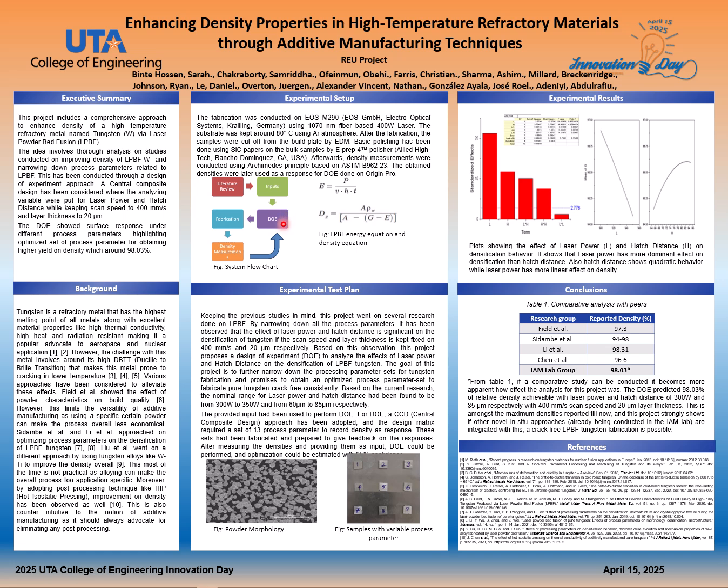We performed the DOE. We did the fabrication on an EOS M290 machine. Then we measured the density following ASTM standard B962 section 23, and then again we gave it to the DOE to find the predictability and the performance of our analysis. Based on the research that we have conducted, we found that they all agree the scan speed is more or less 400 millimeter per second and the layer thickness is 20 microns. So we fixed those, and from the researchers we found a range for the laser power and the hatch distance to be from 300 to 350 watts and 60 to